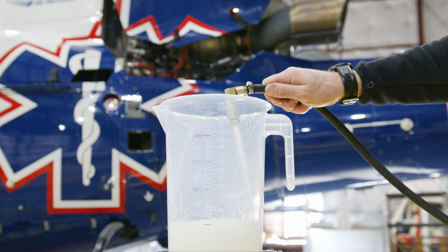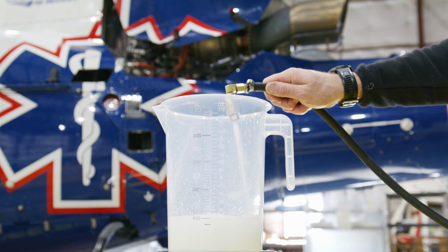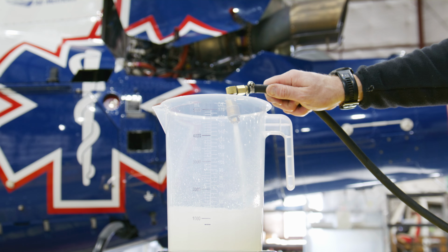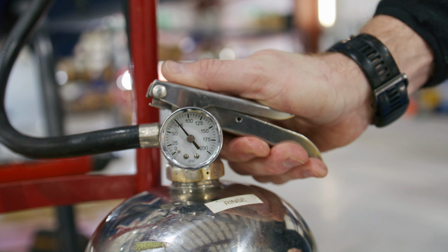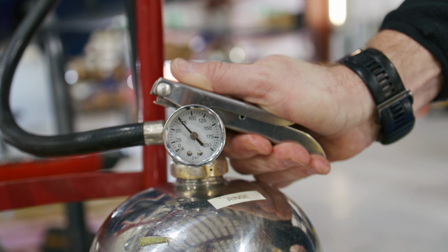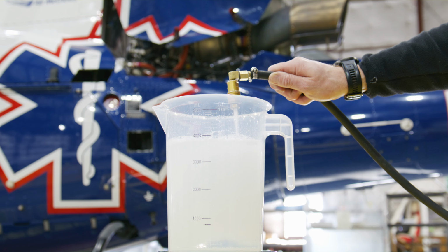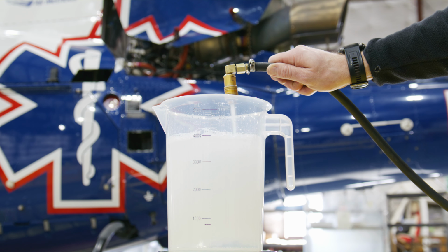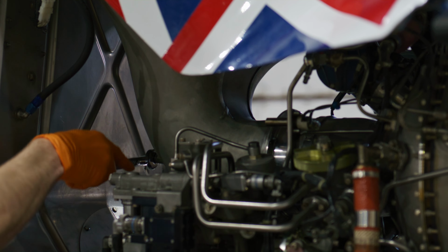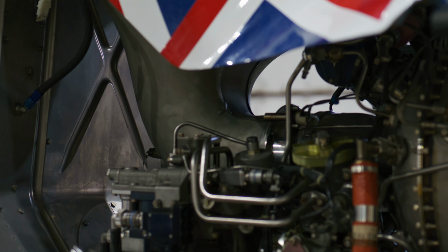Consider the following when configuring your washing equipment. Set the equipment up correctly to make this task easy to perform. Protect yourself from FOD with an inline filter on your locally manufactured spray system. A flow limiter is the most reliable and predictable method for flow control. Be aware of contamination sources with a multi-tank system. Complacency can lead to engine removal for repair.